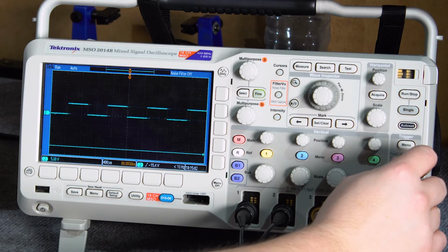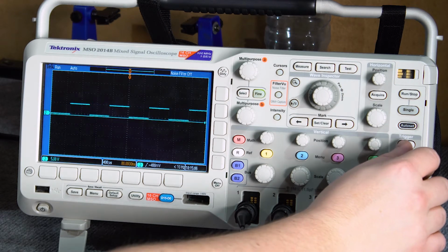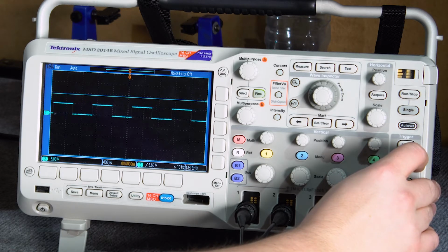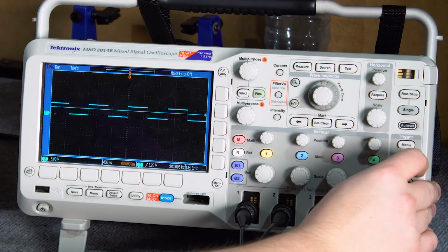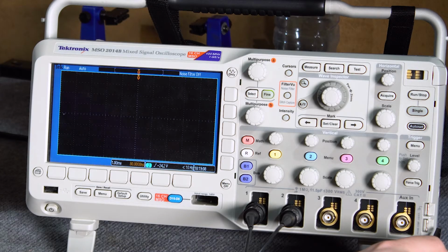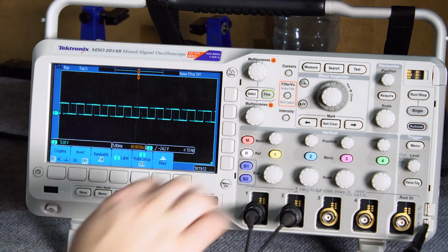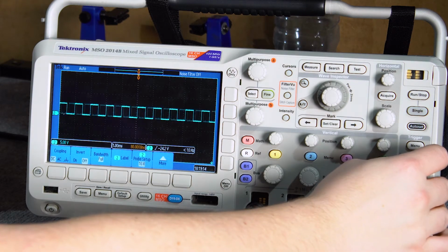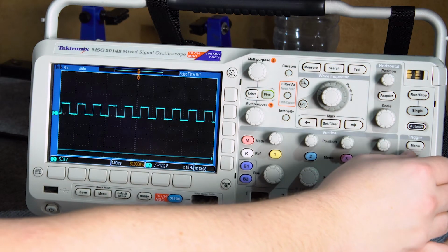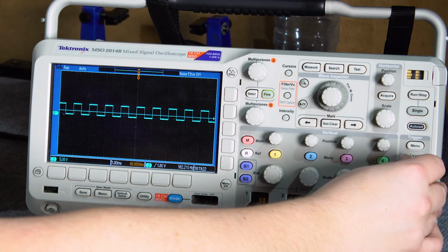The system is used to draw waveforms from the beginning, left side of the screen, at appropriate time moments. If you were to draw the waveform continuously without triggering, they would be illegible and unstable. To set the trigger module correctly, first select the signal's source. These can be input channels or an external dedicated input. We use only channel 1, so we set it as our source. The last in the order is the trigger threshold, level.